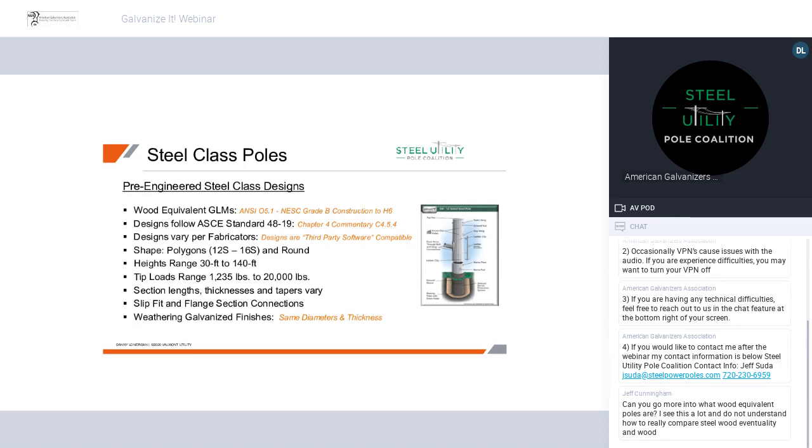The embedment's important. So generally speaking, all pre-engineered structures from a design standpoint are based on 10%. The embedment is based on 10% of the length of the pole plus 2 feet. And that's a complete takeover or move over from wood. So again, it's a basis of design. You'll find most all fabricators do have pre-existing designs. That's their basis. When we get to the software section, we'll speak slightly on, obviously, if you change your embedments, the capacity of that pre-existing pole is going to change too.